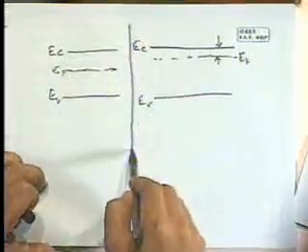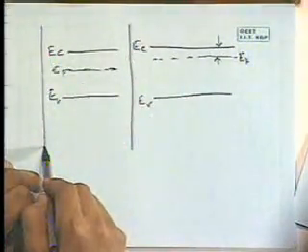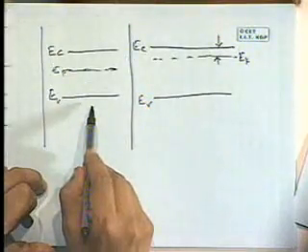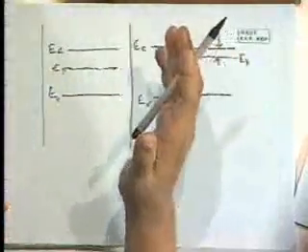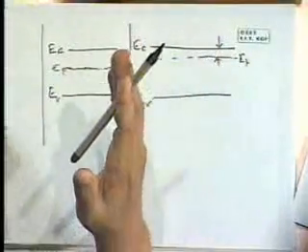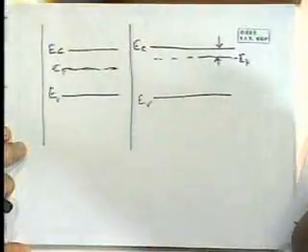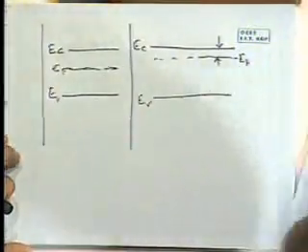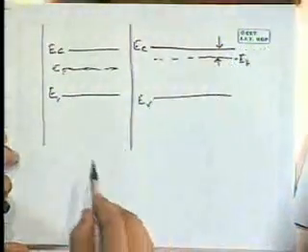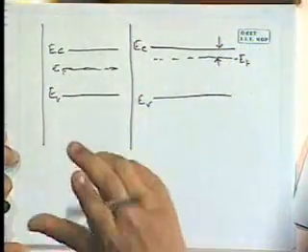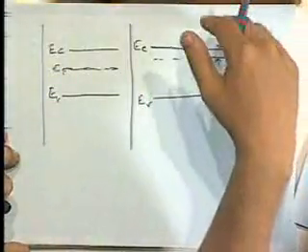And what I'm saying is that the depletion layer reflects this situation, because there are fewer electrons there with respect to the bulk. Actually, all the free electrons have been taken out of there. All we are left with is that space charge. And then in the rest of the semiconductor, nothing has changed, where there are more electrons, and therefore this gap is smaller. So in part of the semiconductor, we've got the Fermi level closer to the conduction band edge, and in the depletion layer it's farther, which implies a bending of the bands to maintain continuity.